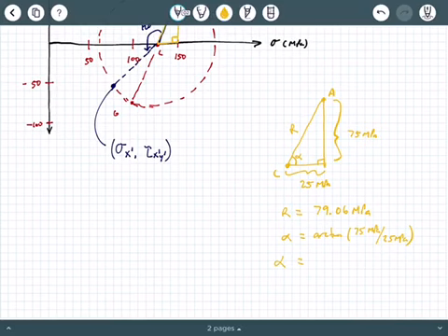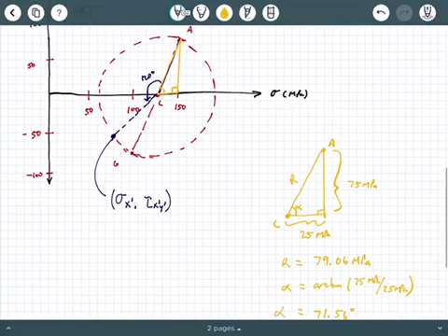That's great. Can I get this interior angle? Absolutely. I'm going to call it alpha, and there are a few different ways of doing this. I'm going to say it's the arctan of 75 MPa over 25 MPa. So I'm punching that in my calculator. That's just the arctangent of 3, actually. So I get 71.56 degrees. So here is that little alpha that I just calculated.